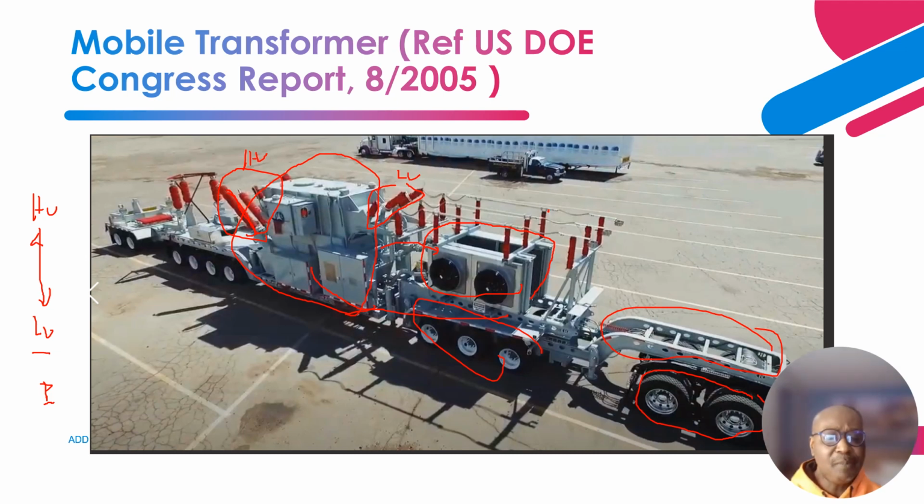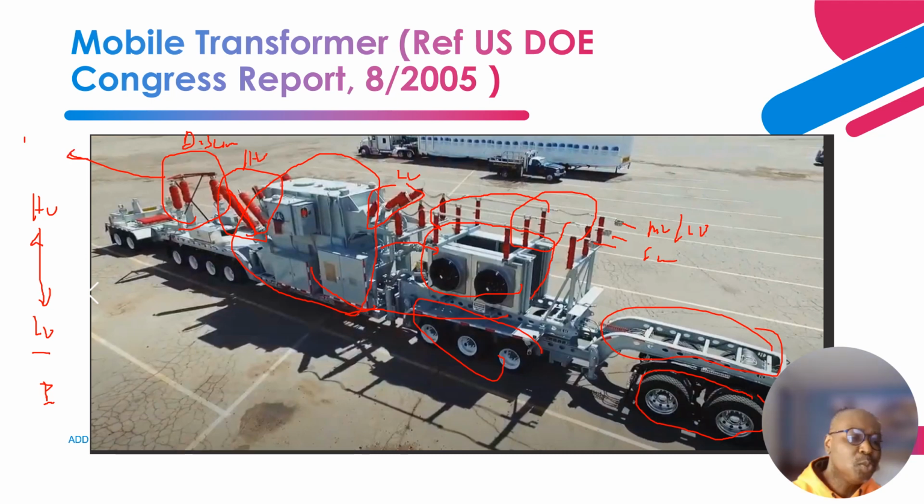And these are the tubular buses, basically from the low voltage side, and you have a disconnect switch that, after that, you can integrate to your medium voltage or low voltage side switchgear that you want to integrate. Okay, so on this side you can have disconnect switches, right? As you can see over here, this side doesn't have a breaker, it just has a disconnect switch.